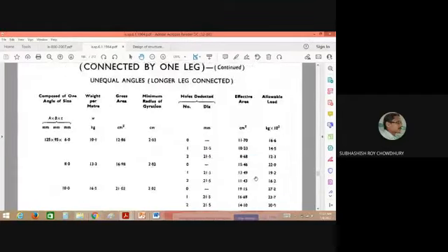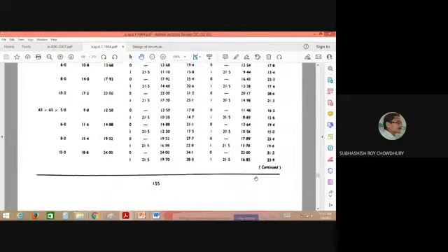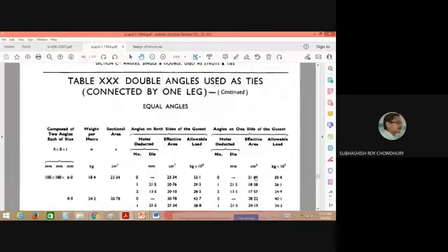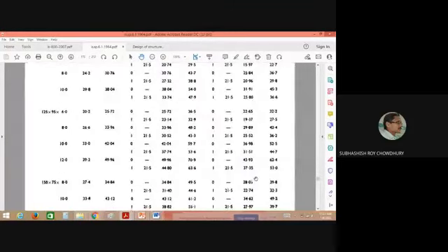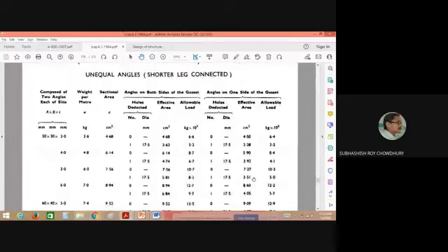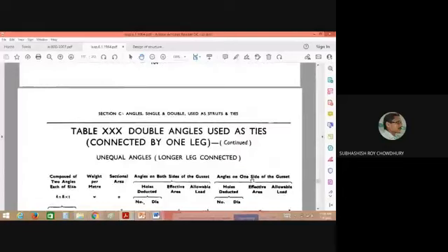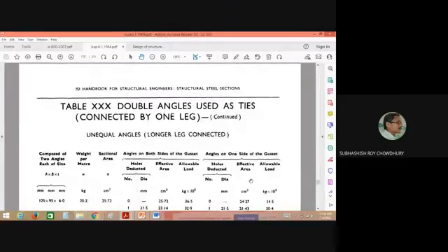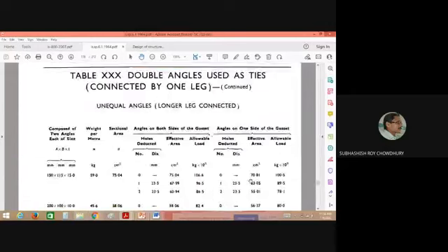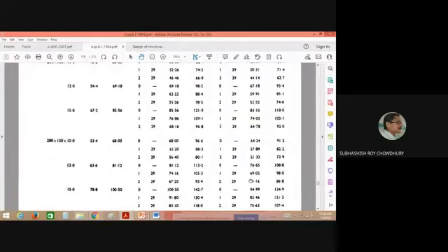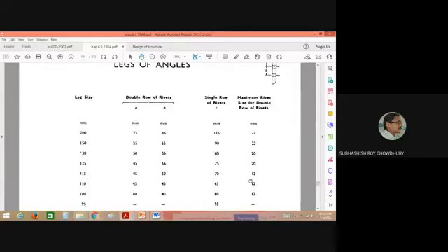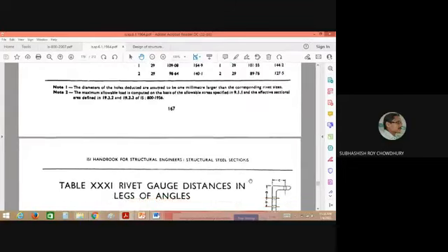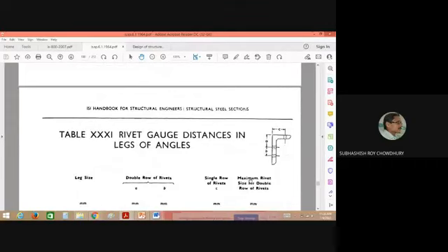The important point that you should remember is that in case of reinforced concrete design, when you have designed a reinforced concrete rectangular beam section, you have chosen the depth of the beam and the width of the beam as per your choice. Just you have considered that the width is say 275 millimeter, depth is say 425 millimeter. If it is 430, if it is 432, there will not be any problem in designing that. Actually, you may give any cross-sectional dimension in that case.